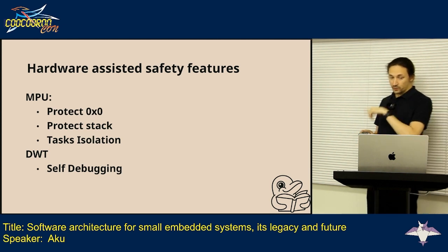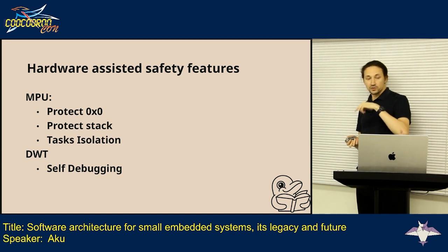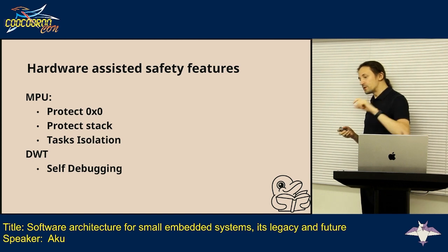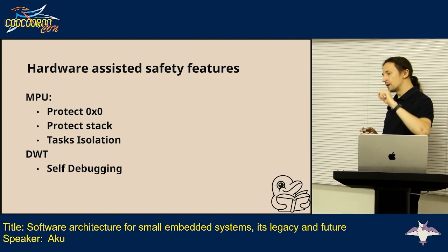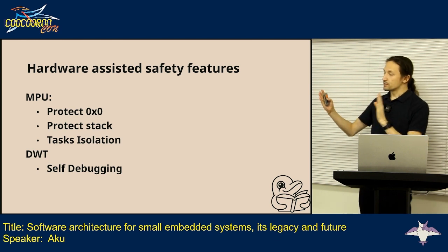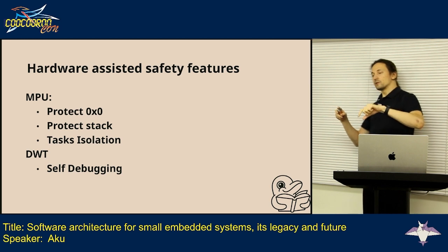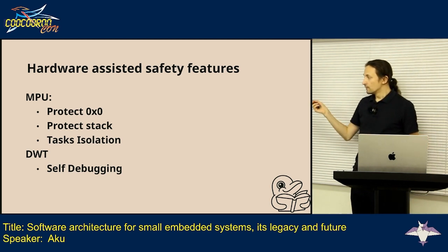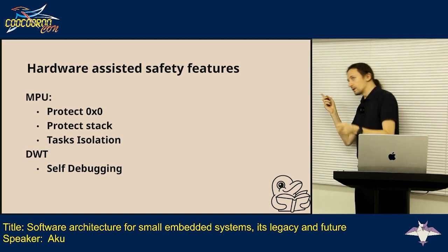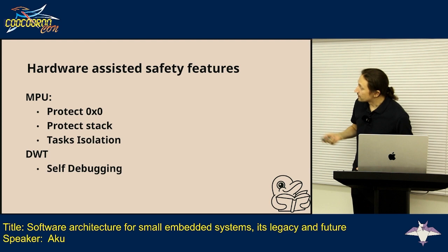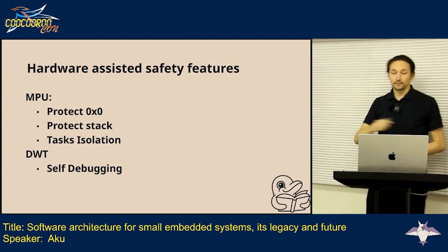So what we're doing, we're using the watchpoint capability. Basically, when we see that some corruption happens in some specific region, and we know between which events this corruption happens, at the first event we usually just protect this region with a watchpoint, and then when someone is trying to write to it, we will get an interrupt, and then we will identify that, okay, someone is trying to write this thing, and we need to debug it.